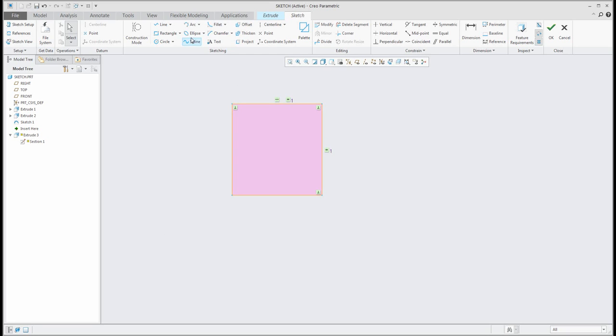And you can use this function again if you work with an arc, for example, and you specify this one, and then you need to create some other shape here. You can use the divide function and select divided points, for example, like this, and then you can delete and add some other shape here. Yeah, it depends on what you need and how you would like to specify it. And then again, delete the unnecessary line. Create the dimensions and finish your shape.